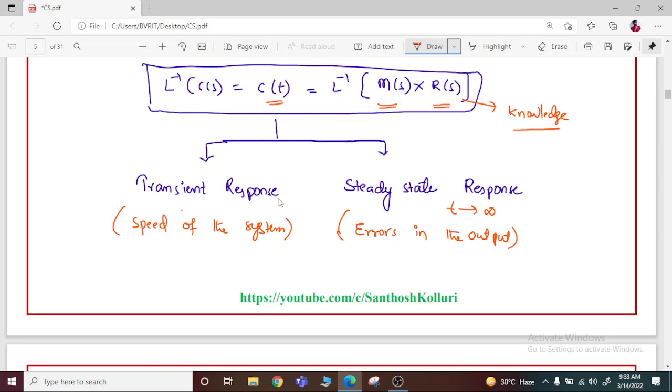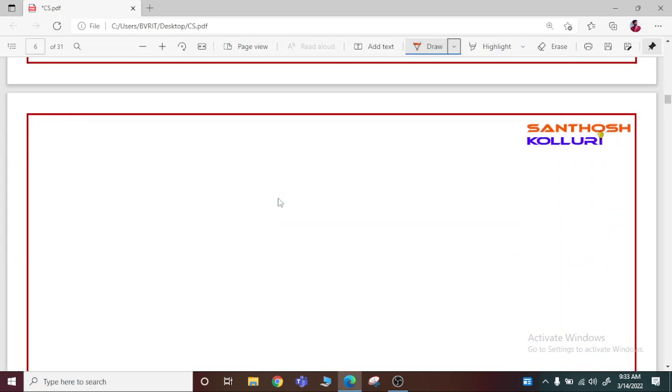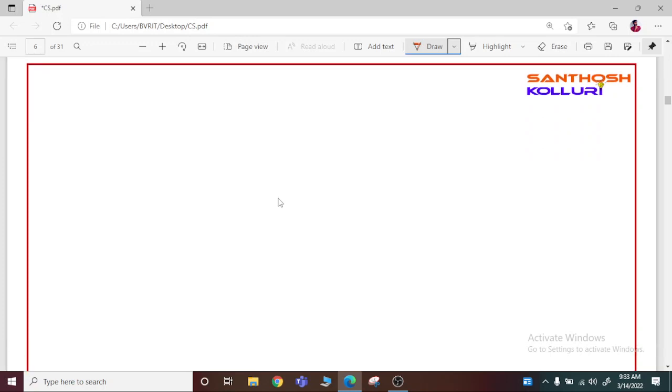In practical cases, it is difficult to know the actual input signals. Generally the characteristics of actual input signals are like a sudden shock or sudden change, or a constant velocity and a constant acceleration. Therefore we have to prepare a few test signals which resemble the original characteristics, and which are used as input signals to predict the performance of the system.